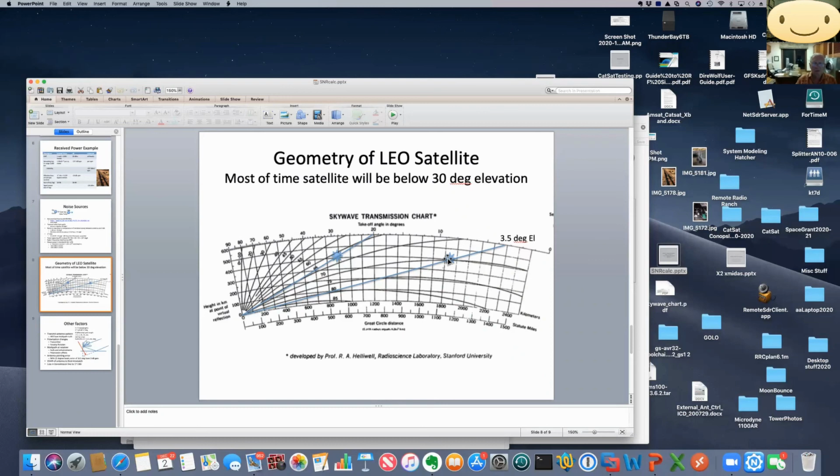So at these frequencies, you don't get any significant bending. You don't usually get any horrible attenuation. So it's pretty much a geometrical line of sight. And if you're lucky, you don't get any radio frequency interference. If you're unlucky and you're in the middle of town next to an arc welding shop, you're maybe in deep trouble.